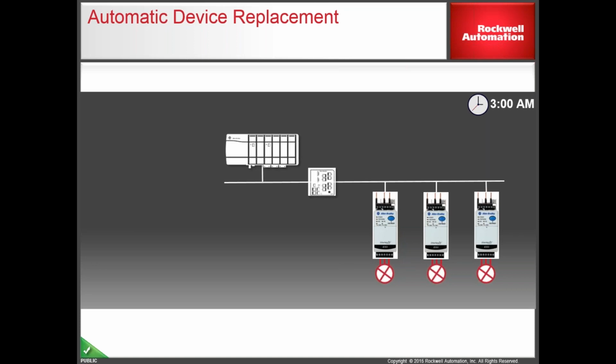The problem we ran into is we configured our E300 and forgot to change, I think it's the motor control mode, to motor overload. Once we configured it and applied it, we realized we didn't change it, so we couldn't change it online. We couldn't do a download because we had 20 other motors running on the controller, so we couldn't do a full download. Did we miss something? Is there a way we can change that? What we did is we had to rename it as a _1 and start over. That's a problem for us.